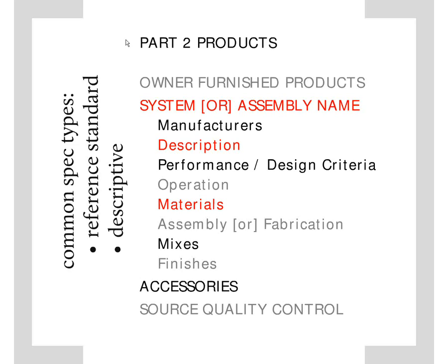So you might have the actual masonry, in the case of a masonry wall. You'd have masonry units. You might have multiple brick types, you might have calcium silicate masonry units, as well as block. And then you might have a separate materials article for the constituent products that go into making up the grout. And then a separate materials article for the flashing and its related accessories, and so forth.